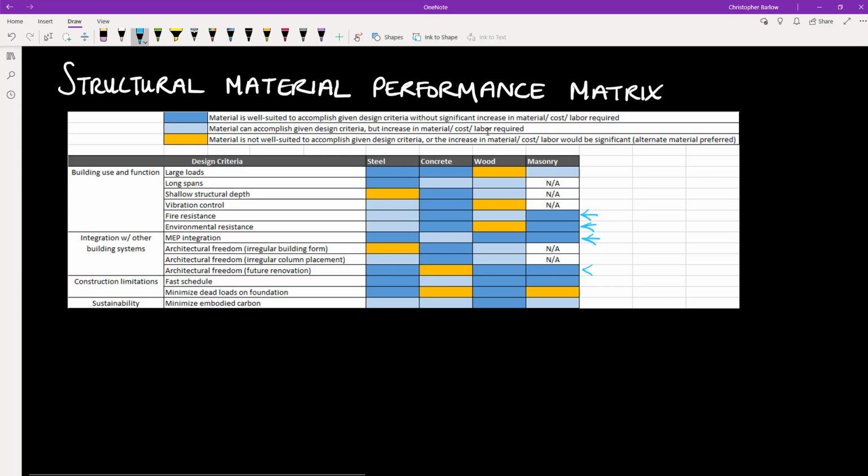Also, holes in masonry walls can typically be made post-construction in a renovation scenario fairly easily due to the modular layout. Masons also tend to be very quick with putting up masonry walls. However, masonry block is very heavy, and generally they do require a fair amount of energy to produce.